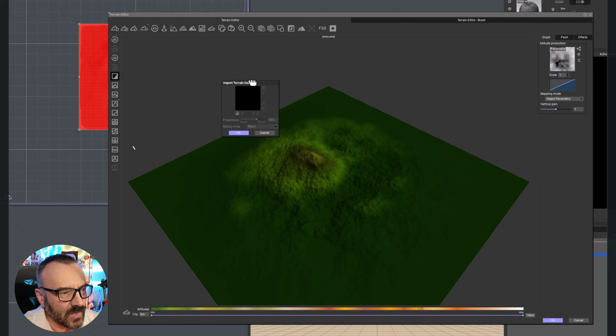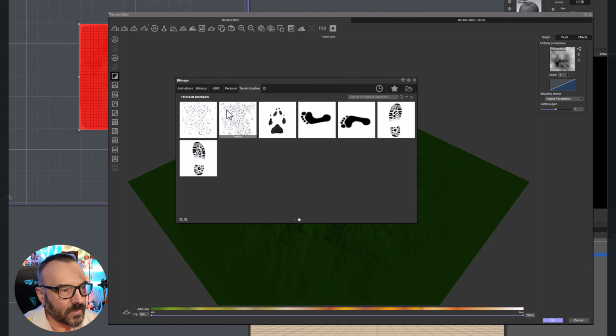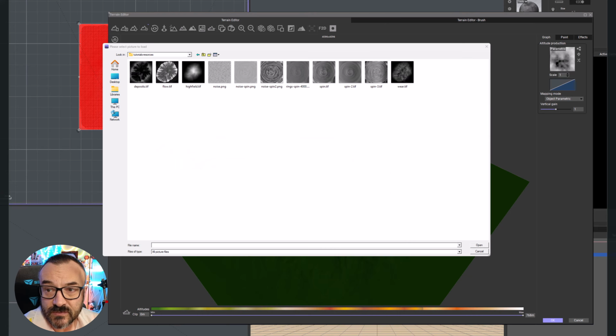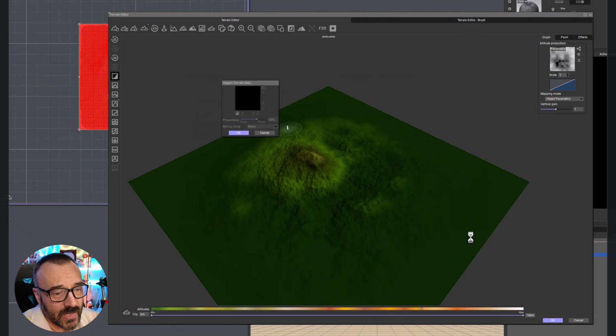Now we're ready. We click on import terrain, and right there where it says load, let's click on this. It opens our preload, and right here you can see the open folder icon. We need to click on this, and after we navigate to the right place, we can go ahead and select Highfield. Notice this is a TIFF file. It means uncompressed, so it's best for resolution. I do not recommend using JPEG. Mostly it's high compression, because they will have artifacts which will affect your terrain. And in the end, you'll see your terrain looks blocky, so it does not look very good. Okay, let's go ahead, click open, and you can see right here it's preloading.